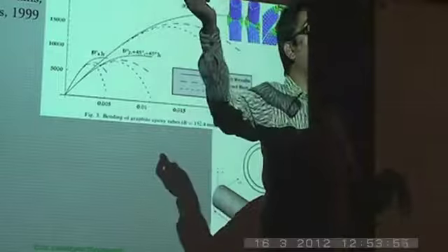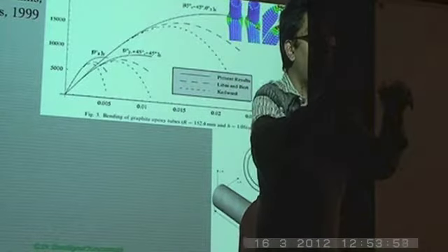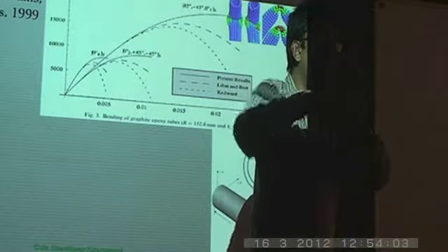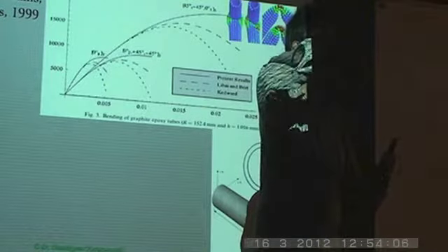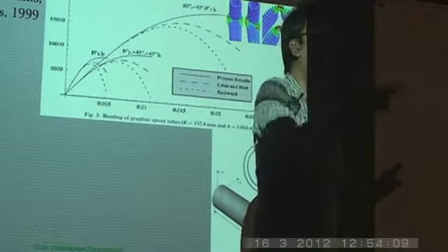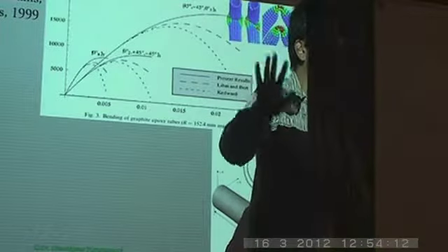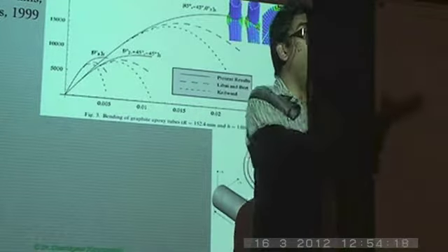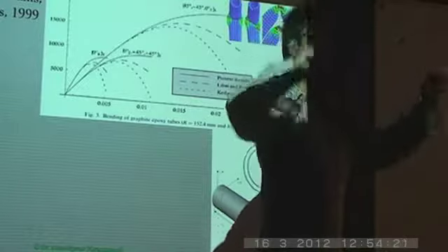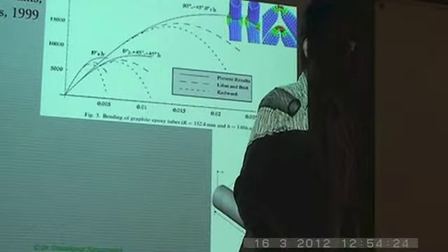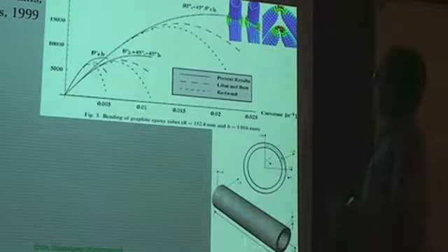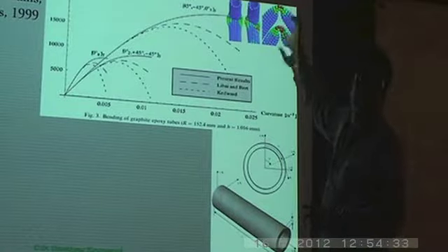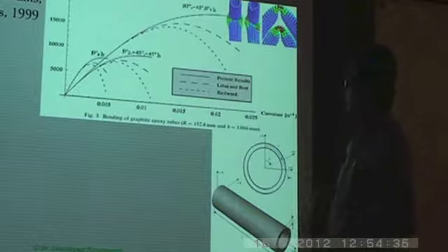Whereas the kink that I was talking about earlier is a kink in the entire structure. See, in a drinking straw, it's not a local phenomena which is happening when you bend it beyond a particular point. It's a kink which basically forms. But in engineering structures, unlike in a drinking straw, that is not what happens first in most cases. It is the material failure and or the local buckling which happens prior to the overall global 1D instability. Yeah, so basically you see these exaggerated situations where you basically see what is happening, and also you see the stress becomes fairly large at those locations.